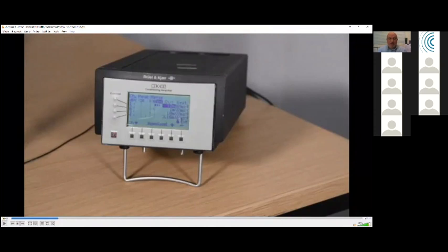So here we have a conditioning amplifier, and that allows us to go to the calibration charts for the force transducer and for the accelerometer, and to put the associated sensitivities into the system. We can also change the frequency range on the conditioning amplifier, and we can change the gain for each channel. Now, because we've got two transducers, we have to have a minimum of a 2-channel analyzer. Most analyzers now have more than 2 channels, but you need at least 2 channels.